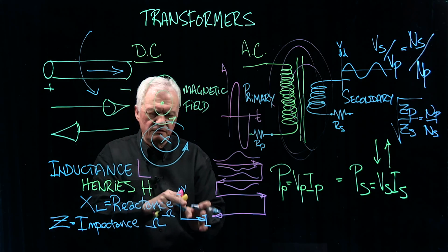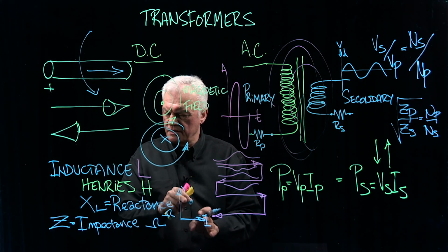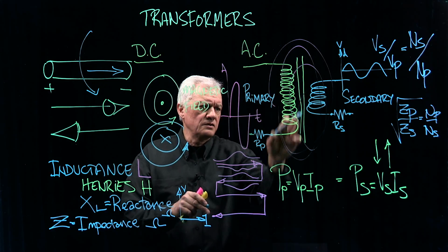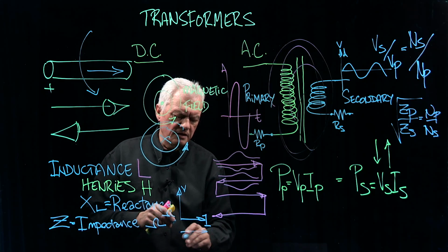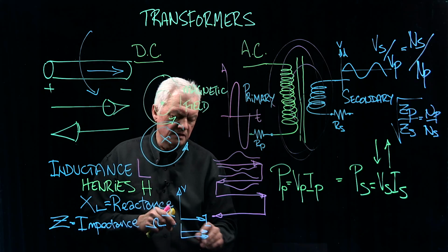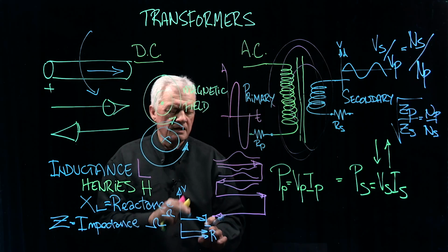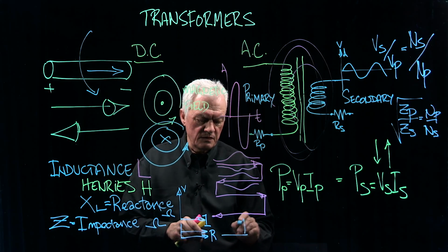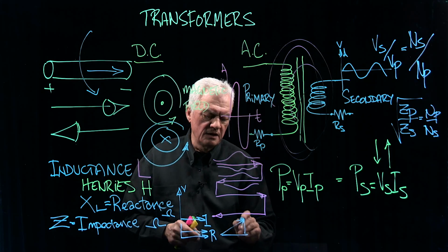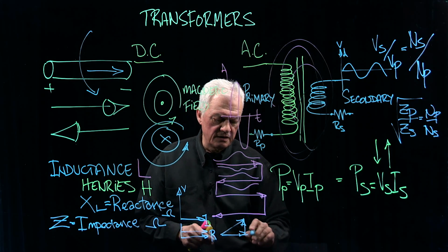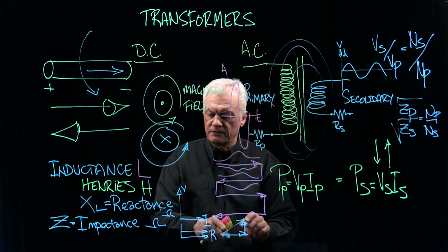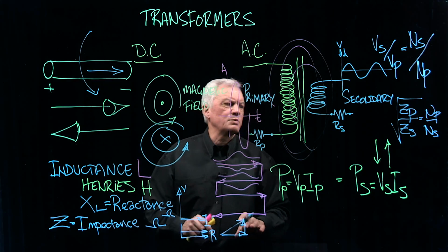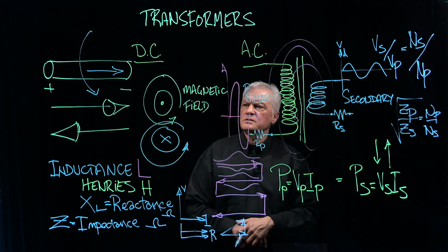And because the voltage is leading the current in the inductor, this is known as an inductor, but in the resistor, the voltage and the current are in the same phase, okay, for the resistance. Then in order to calculate the two, and we won't spend much time on it here, we say the impedance is equal to the square root of the sum of the squares of the resistance and the reactance. But again, I'm not really trying to cover that today.